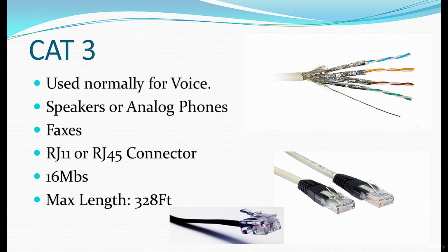Cat 3 is normally used for voice. You can use it for speakers or analog phones connected for faxes. They use an RJ11 or RJ45 connector. It can be used up to 16 megabits a second, and the max length of the cable can be 328 feet.